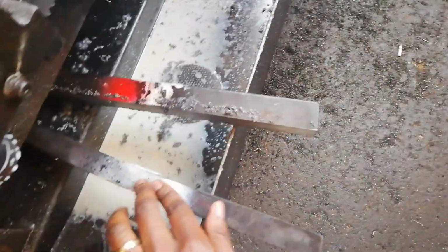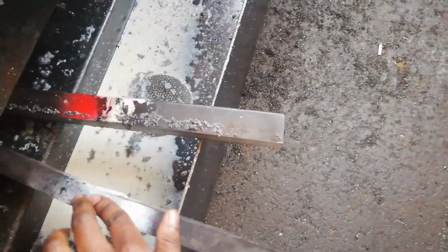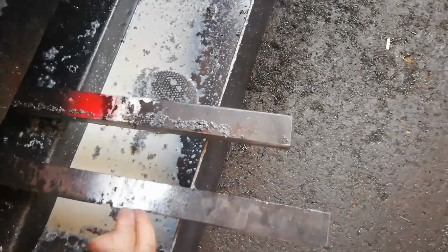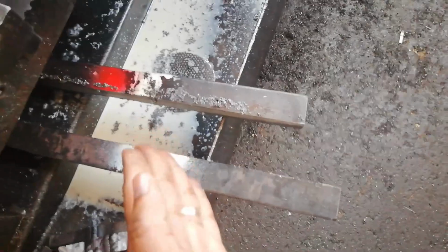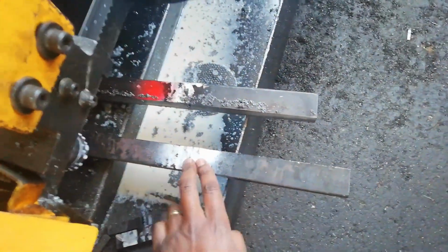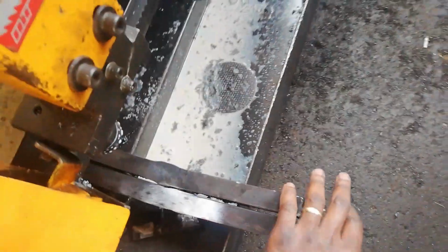After discarding this part here and this one as well, these 2 parts we discarded, the first 20 to 25 millimeter of the plate, right? Because remember, this is just the beginning of the plate. So if you want to test this part, you might have a lot of stuff that you don't need in your sample, because you know what I mean, the beginning of the weld and the end of the weld, whatever you call it, right?